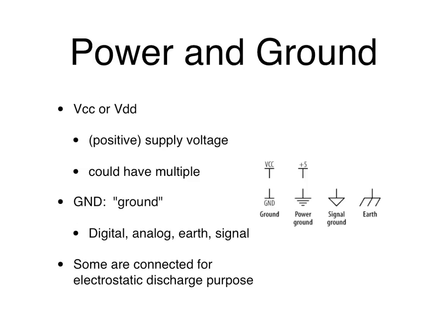And why do you need a ground? Because you really need a reference, right? How do you know if you have a voltage that's high or low? It has to be relative to the ground. Without the ground, you have no reference, and it could be anything. That's actually a common mistake for a lot of beginning embedded system projects: they have a bunch of things, but they forgot to connect the grounds together. So the port pin is connected, but it's not relative to any ground, and you can't see any effect. So the ground has to be connected. That's very important.